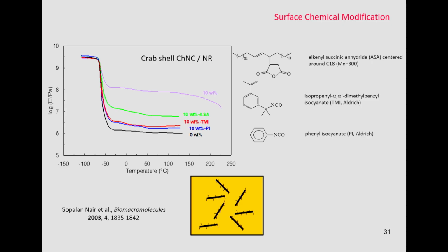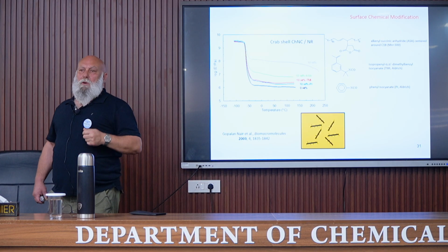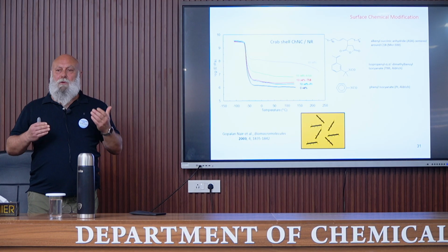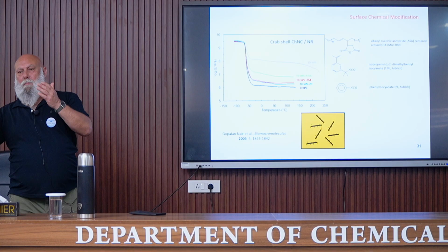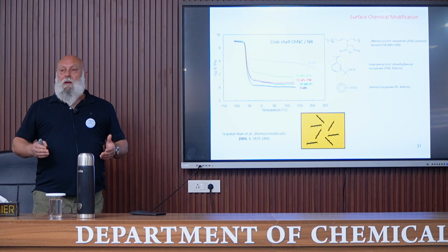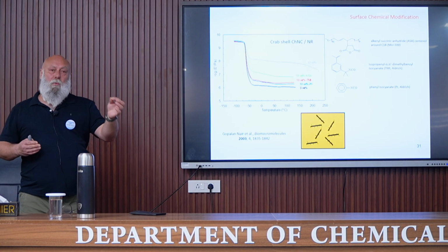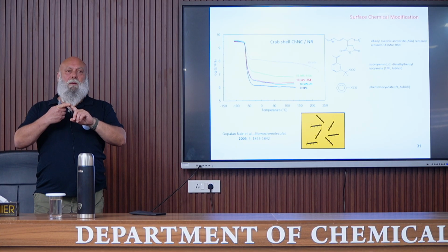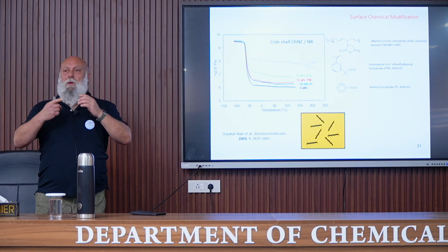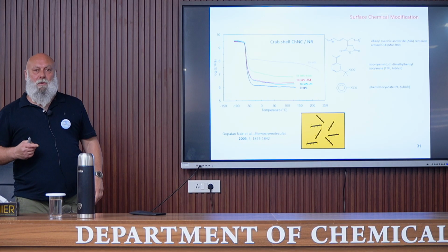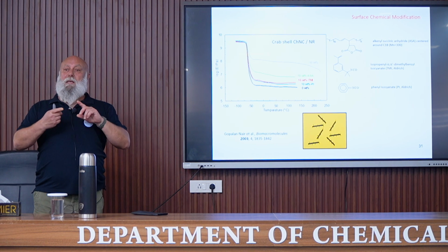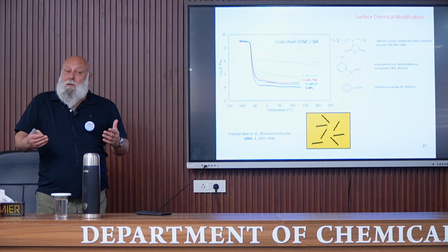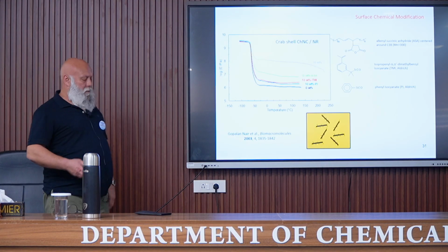That seems contradictory to microcomposite, because for microcomposite, when we compatibilize the reinforcement and the matrix, the mechanical properties are increased. In this case, you understand that what we want to promote is the interaction between the nanocrystals. And if we have a good adhesion between the reinforcement and the matrix, of course, it is at the expense of the interaction between the nanocrystals. But for this, of course, it's necessary to have a good dispersion.